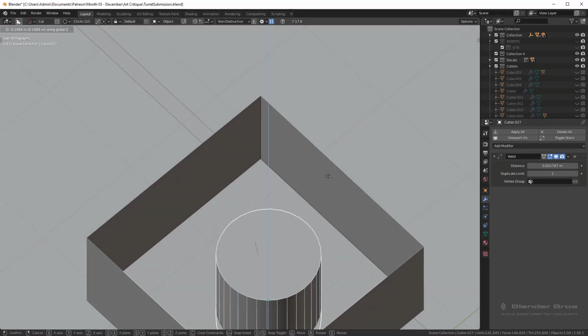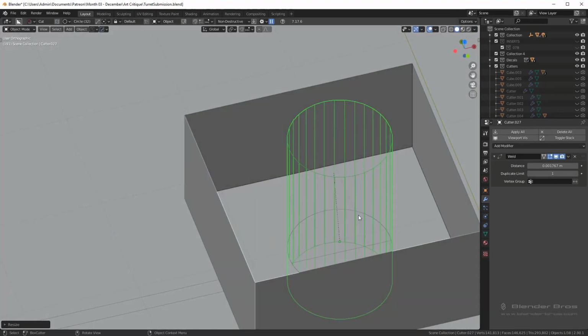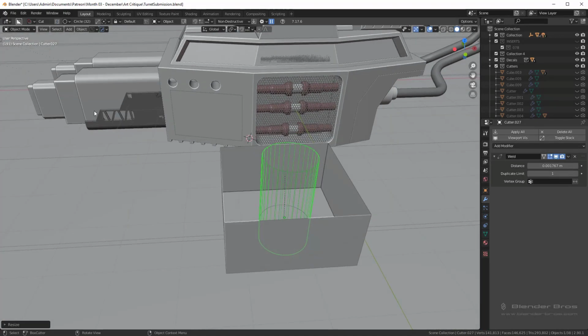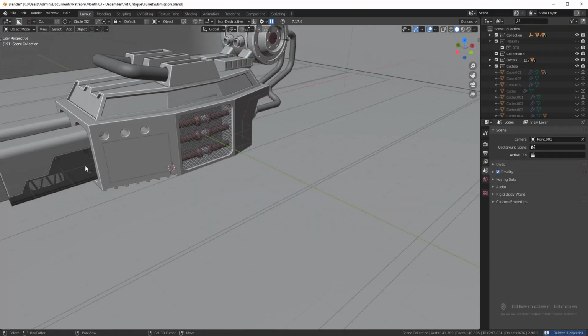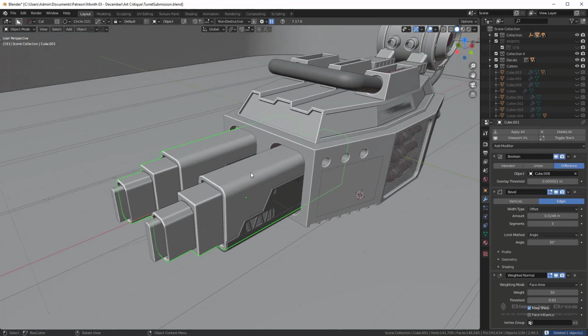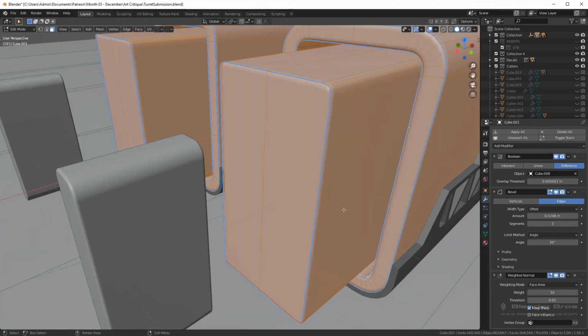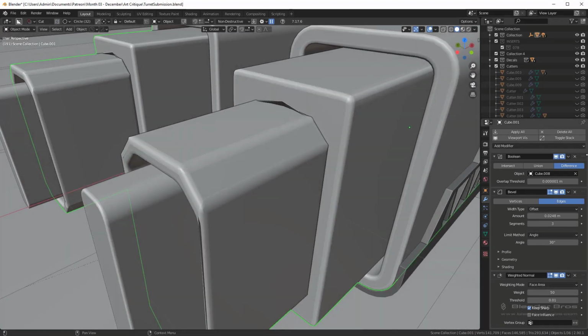Now it's actually a difference, and we could scale this up and have a proper hole in the bottom. A similar type of calculation is occurring over here, which is why I was having some problems, and I just couldn't quite pinpoint it because it wasn't as obvious, but that's essentially what is happening with this one. So sometimes you might notice that, as a matter of fact, your union isn't really working as you would have expected. But anyways, yeah, that would be my recommended fix. Switch it to difference and it'll basically give you the same effect.